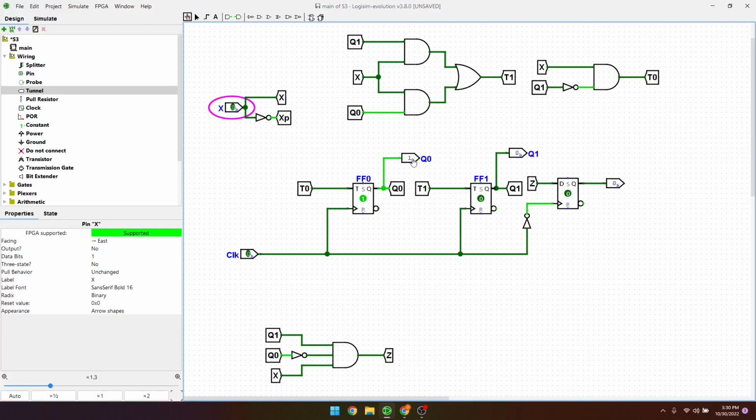You read it from right to left, I guess. So it'd be 0, 1 represents that. And if we're not putting any more money into the machine, it's just not doing anything. But then if we put in a nickel, then it's okay. So this is positively edge-triggered. So when I click this, it's going to go 0, 1, 0, 1.